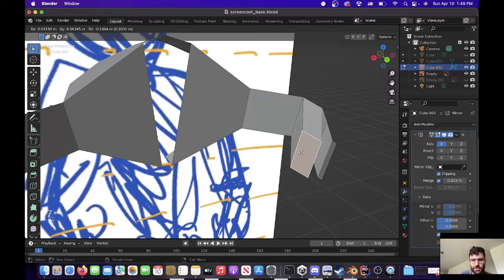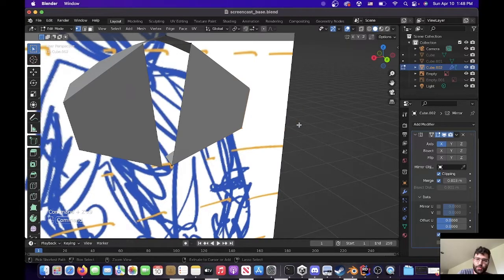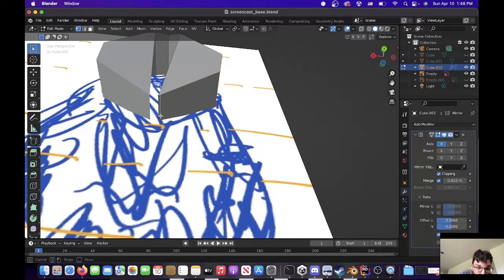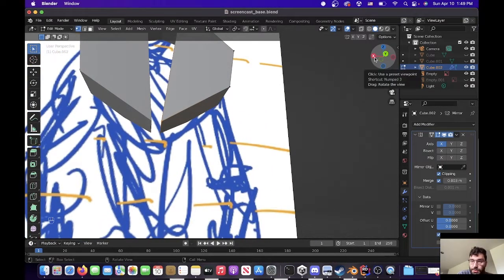And you can constrain it to axes. So if you double tap an axis, it'll be local. If you single tap an axis, it turns off and all this. Anyway, but undoing all of that, what we're going to do is, see right here, we have our edge right here. We need to extrude out.